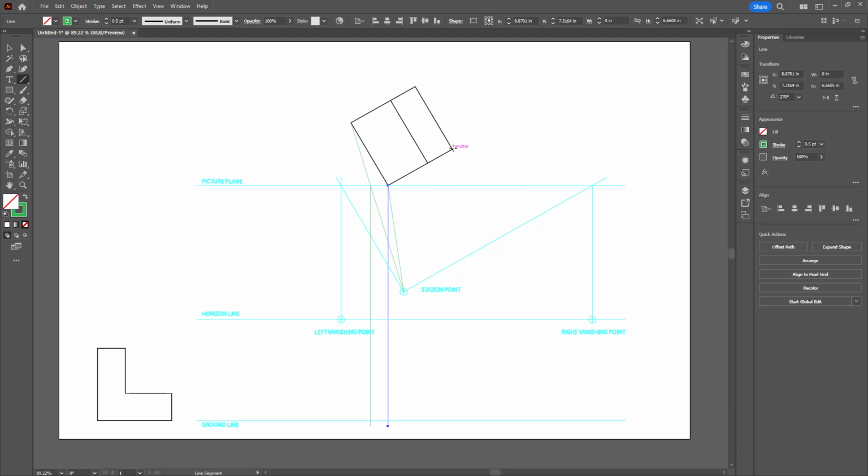And we can do this one here. First off, I'm just going to try and get my cube, so we understand this is basically a 2-inch by 2-inch cube. So that's good. Again, intersection, drag it down. Now we can use our side view here to create our heights. So we can just drag across here, drag across here, and drag across here. We've already got our ground line, so I don't have to do that, so I'll just undo.